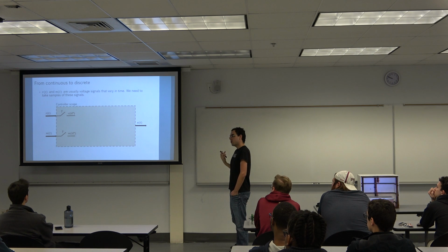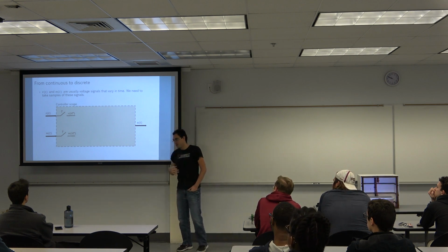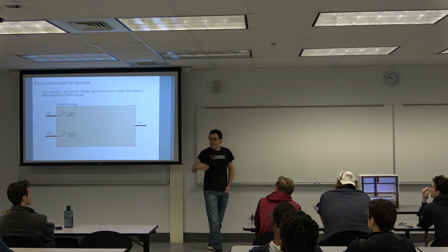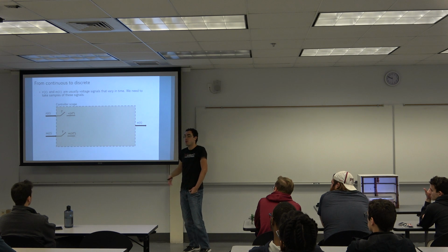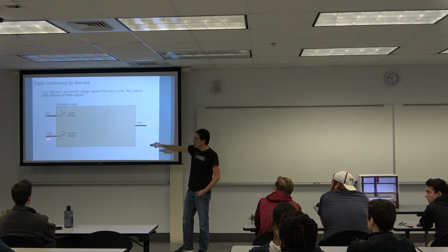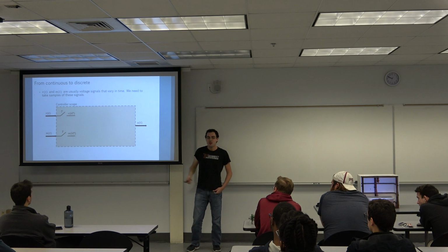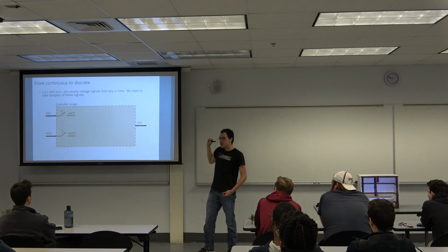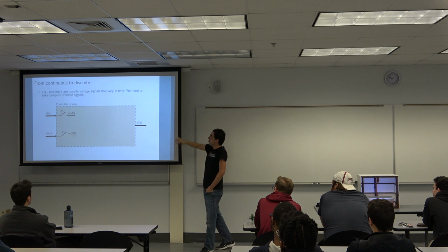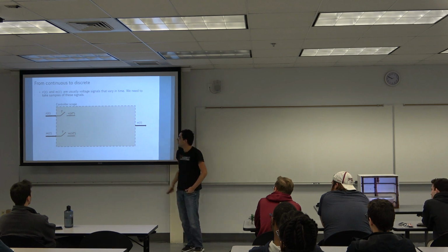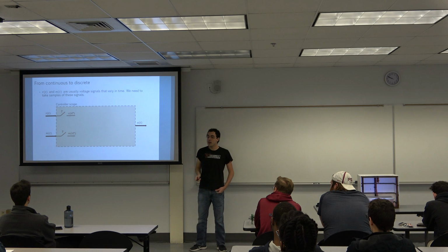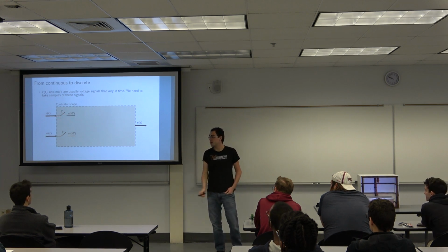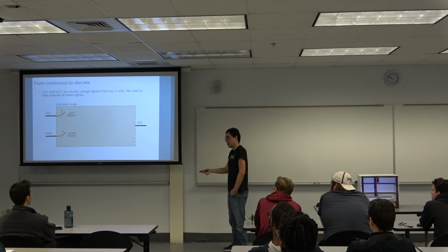So for that, our Arduino can only do stuff in finite time or finite cycles. So we're sampling at some sampling rate. So the switch here represents our sampler. So our sampler is taking a measurement and then holding it somehow for our Arduino to perform its computations. So this means that our signal from the continuous time now becomes a signal in the discrete time, R of kT, where k is an integer number and capital T is the sampling period.